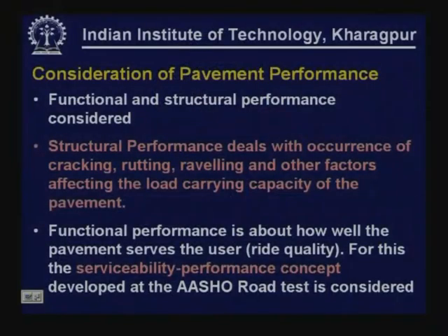For this, the serviceability performance concept is used. How well the pavement is able to serve, what is the level of serviceability available at a given point of time. This concept is used in AASHTO guidelines for describing the performance of the pavements. In fact, this was a concept that was developed during the AASHTO road test.